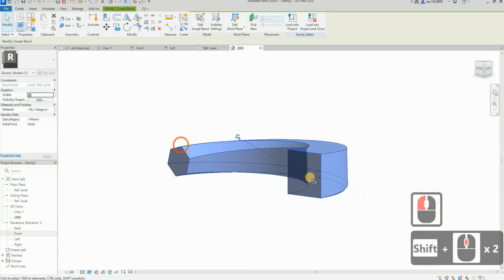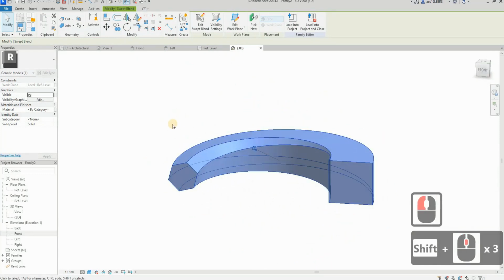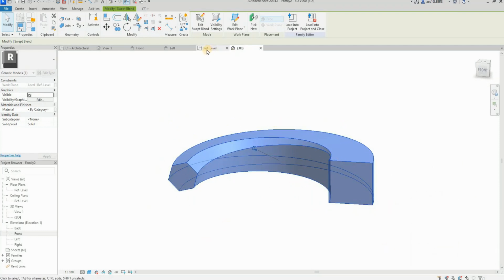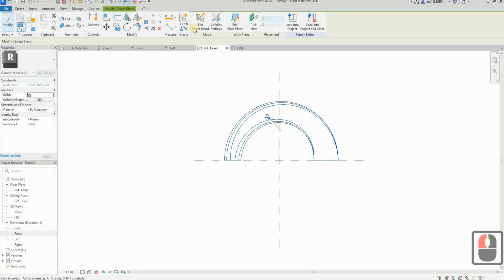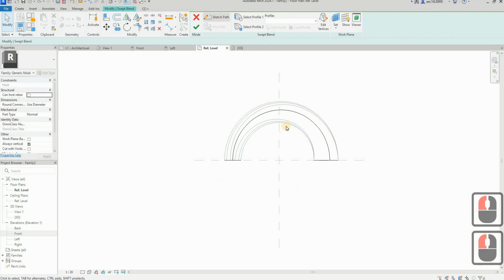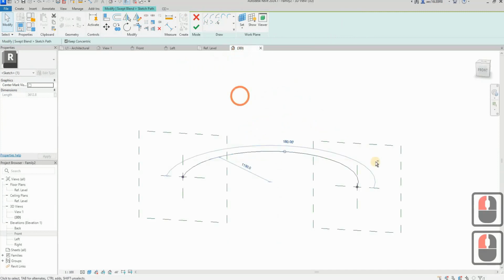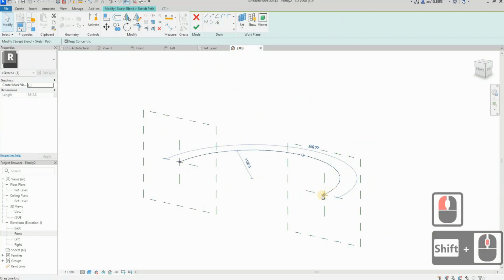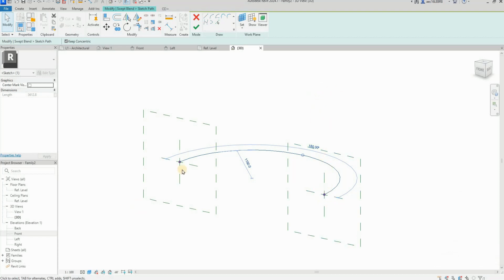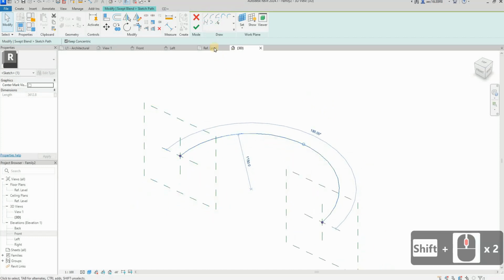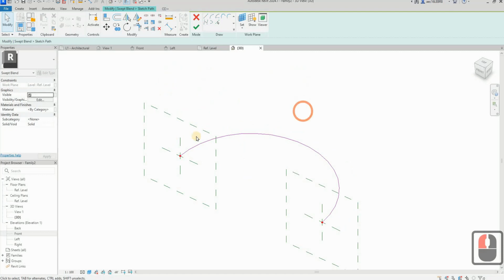Okay. So if you realize that Revit allows you to sweep your path along the same axis like this, it means that your path, let's say I edit the sweep blend, I sketch path, your path is always at the same reference plane. What I mean is I cannot move this dot over here to the z-axis at a higher path. So it always sticks to the 2-dimension plane. Okay, so that's the use of sweep blend coming in now.